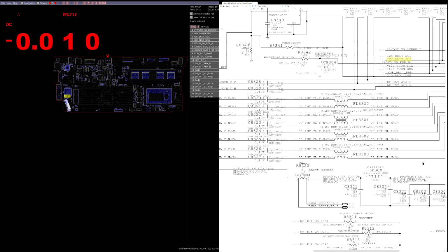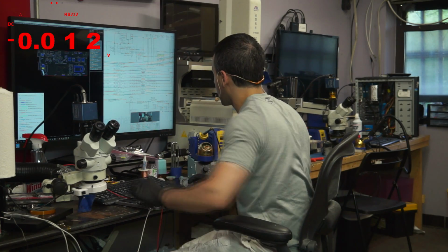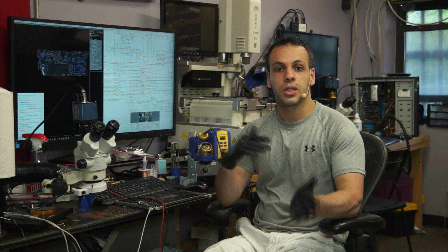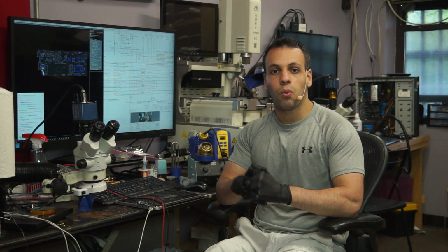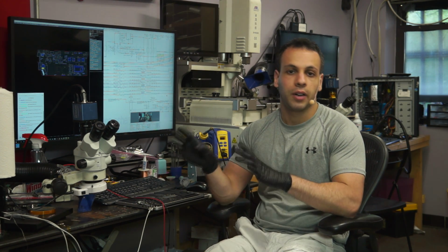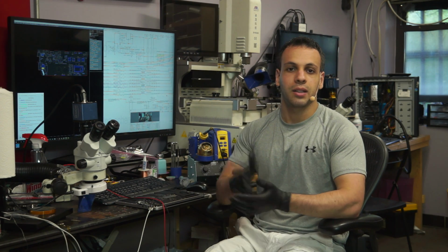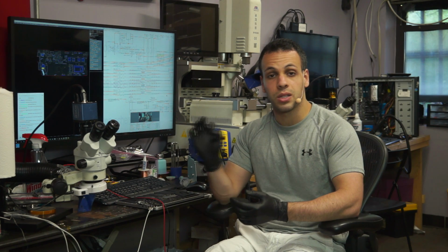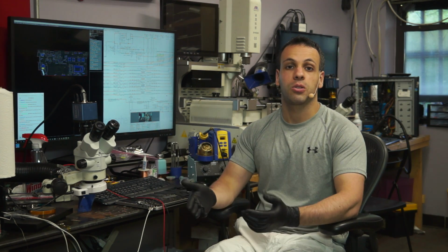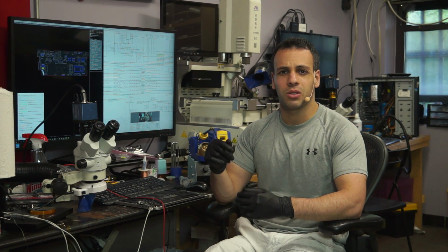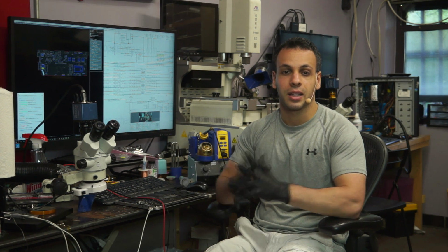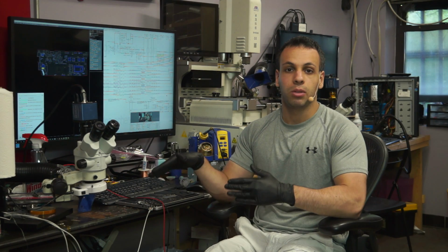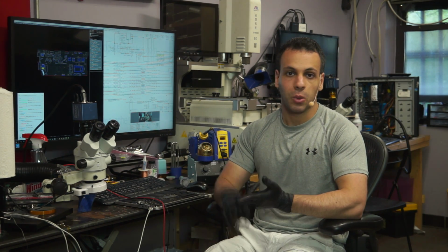Also, one thing to keep in mind when it comes to defective screen cables, this is something that I get asked a lot. When you are talking about LVDS, which is the old signaling protocol for screens, you could have one of the lines be a little intermittent and you would get a funny looking image. With DisplayPort, 99.99999% of the times, when you have an issue on any one of those display signal lines, you will get no picture at all. So if you're getting kind of a fuzzy image on your screen or an image that kind of goes in and out or anything like that, most likely it is not an issue that has anything to do with the cable. It's either a bad screen or a bad board.